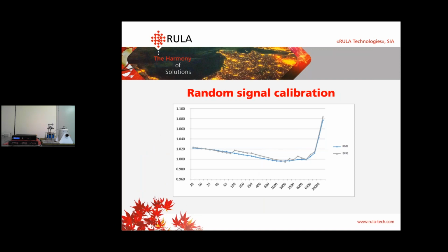There is a question about the distortions. Is it possible to correct the distortions? Unfortunately, the distortion comes from the shaker and there is no way to correct it. But you can use a filter. We are using a filter which takes only the main harmonics and filters all other frequencies and harmonics. Do we have any other questions now?